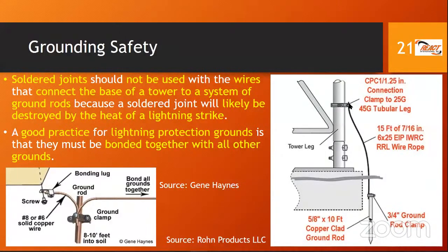Note that you should not use solder. You should not solder these connections at all. That is actually very bad practice. Use compression, or if you're doing some sort of cadweld or something like that, but do not solder these connections. The simple reason is that if there's a lightning strike, the lightning strike may evaporate the solder. You don't want that to happen.